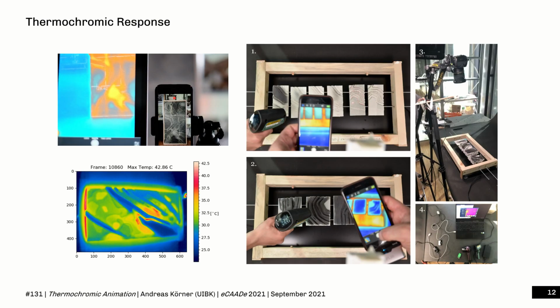In response to the research questions, the experiments led to the following findings. Intricate surface articulations lead to a stronger thermochromic response. This includes imperfections, tool traces, paint pooling, and coating evenness. Thin and porous geometries perform better since their thermal mass is comparatively low. They also have a higher surface area. Cavities and inclusions have an impact on the thermochromic response. The trapped air insulates and impacts the heat transfer path inside the geometry. Flat backsides and reliefs perform worse than geometries that are equally intricate on both sides.